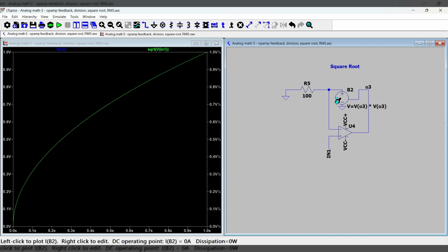Not going to go into this further. It's essentially just inversing whatever function that we put in the op-amp's feedback, and the function that we're putting in is the Gilbert cell that squares the voltages. So therefore, the op-amp will square root the voltage.